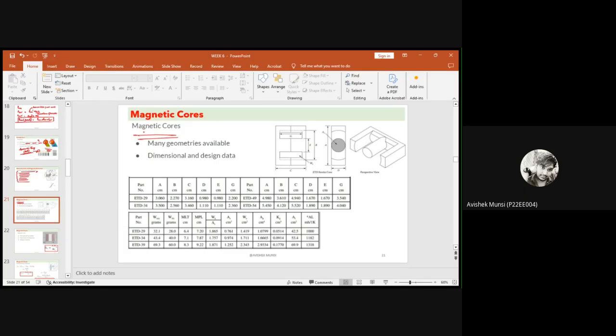In the case of ferrite or laminated metal alloy core, the required gap is physically discrete. But in a powdered metal core, the gap is distributed among the metal particles. So you can paradoxically say that in virtually all magnetic materials, magnetic energy is stored in the so-called non-magnetic gap.